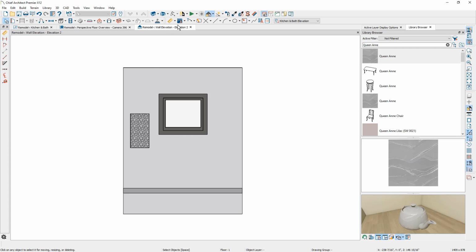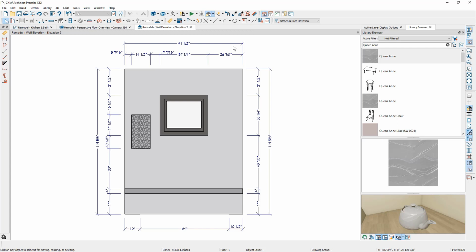Let's use the automatic NKBA elevation tool. We'll position that. I'm going to grab the niche, come up to the dimension, and enter in 6 inches from the window casing. I'm not going to worry too much about the floor to bottom. That looks okay to me. While the niche is selected, I'm going to use the Copy Reflect About tool, use the Reflect About from the room, and exactly position that niche.